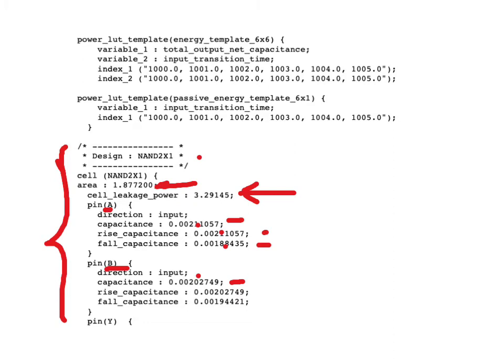Now, so far we have discussed how you would obtain the characterized values of leakage power in a gate, as well as the power of charging the output capacitance. But we've not talked about how you would estimate the short circuit power, which is still a dynamic power, but is not directly related to useful computations. We can proceed to study that.